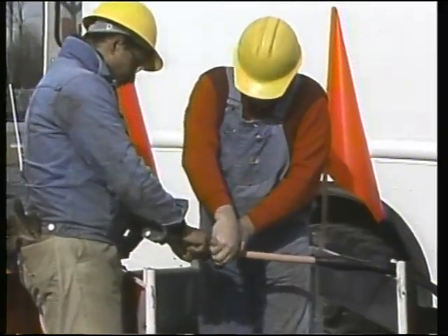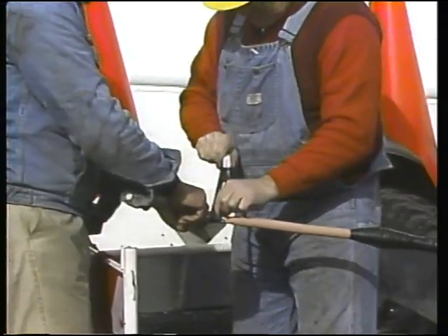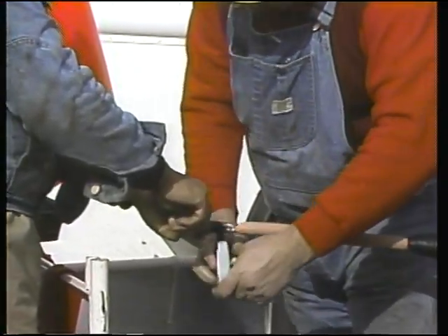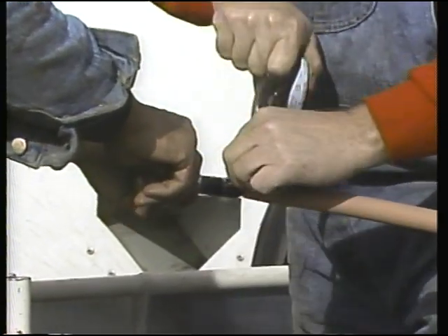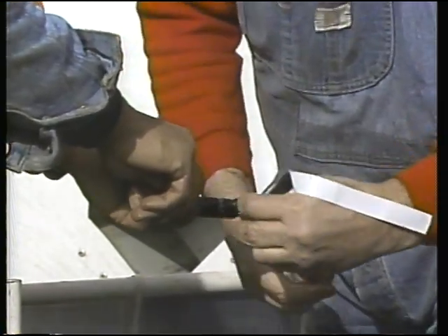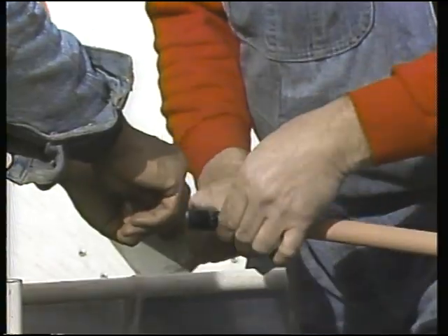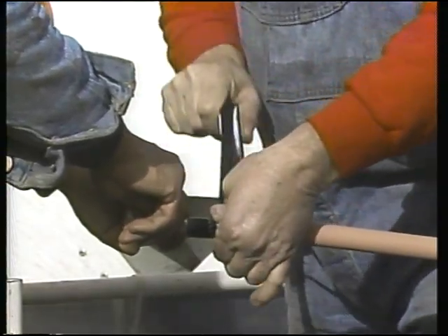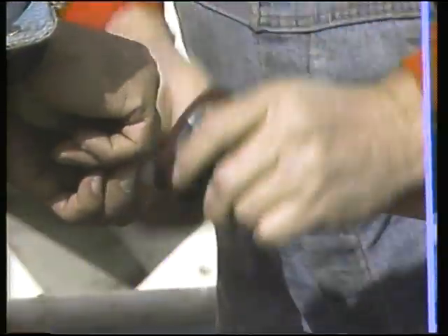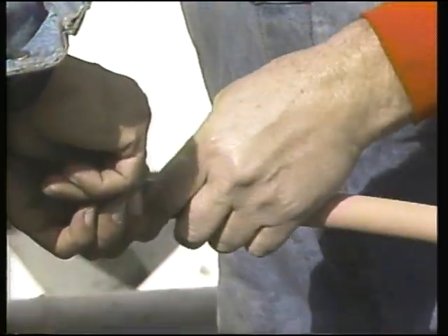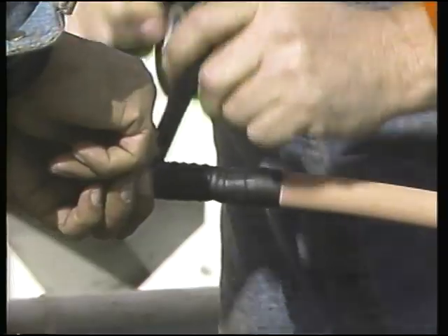A second, smaller cone is then built near the end of the cable to increase the creepage distance between the conductor and the insulation shield. It also seals the cable end. To build this cone, semiconductive tape is first applied over the lug barrel and over any areas of exposed conductor. Then, rubber insulating tape is applied to build the cone.